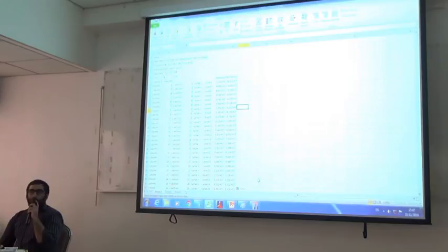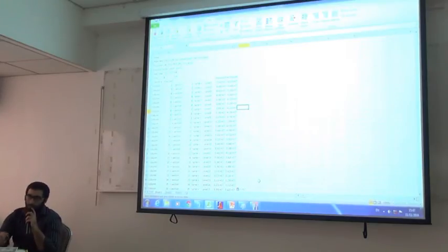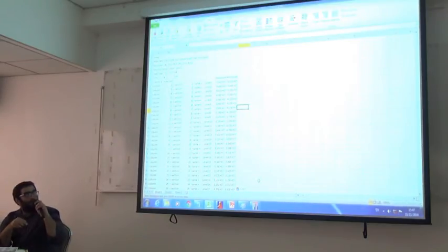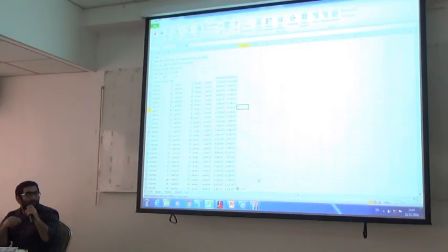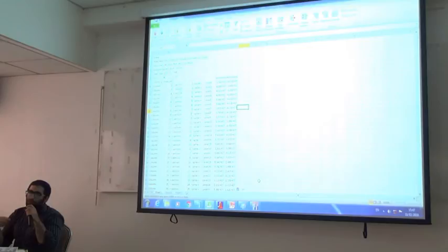Okay, so these are the section cut forces that you already got in the Excel file, and then you can use these numbers to do whatever you want to do with them. You can design your shear walls and everything, right? Now I will repeat the same process for extraction of the drifts also.